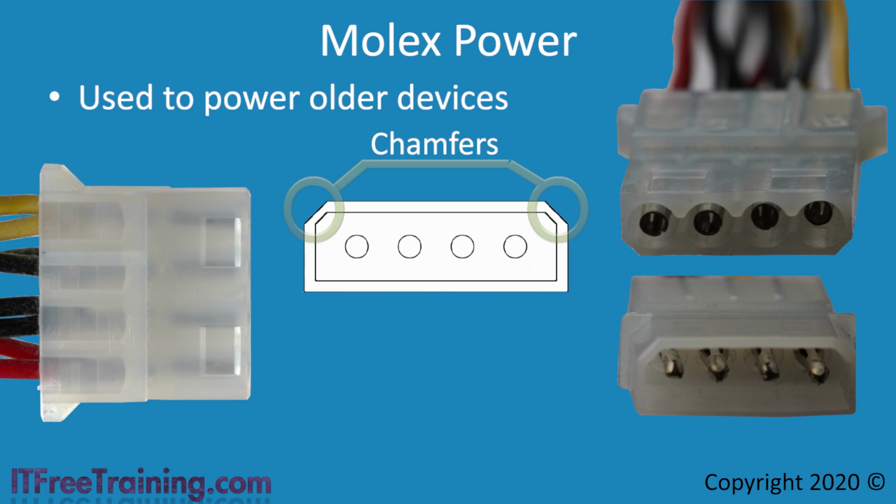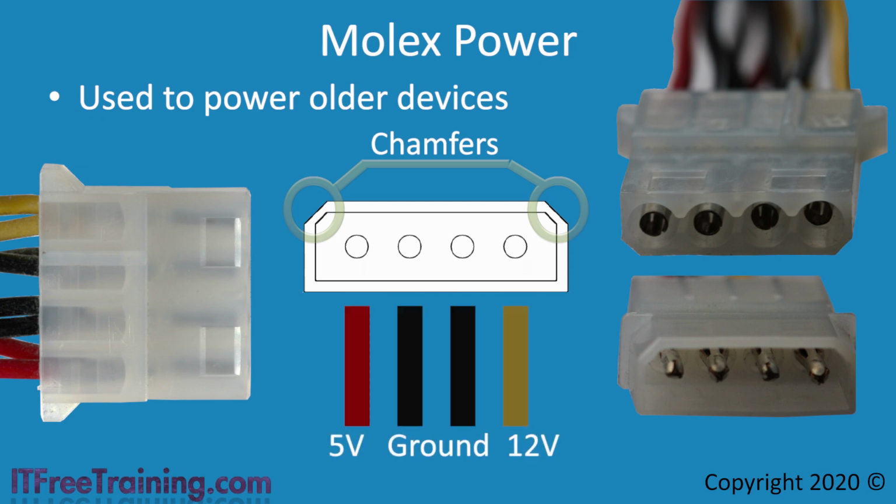It is possible, using a lot of force, to get the connector in incorrectly, but this will most likely damage the device. If you do get the Molex connector in the wrong way, the power going to the device will be swapped. As you can see, the red wire is 5 volts and the yellow wire is 12 volts. When the connector is reversed, the voltages will be reversed and potentially the device connected to it will be damaged. Nowadays, this connector is mainly used for older hard disk drives and case fans.